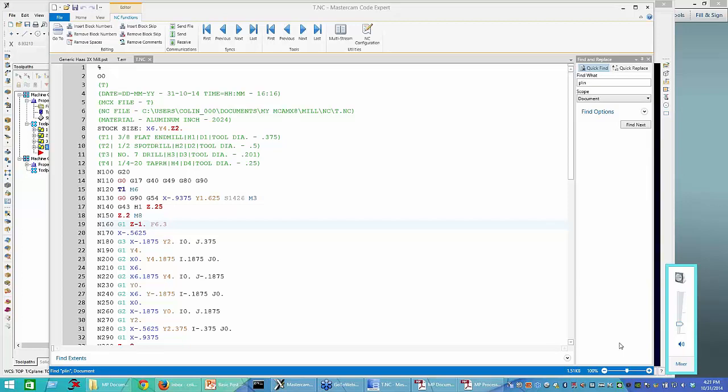One more here. For finishing toolpaths, can I output the step over or scallop height in the header of the posted file? That's coming in from Tom. Yes, you can. It depends on whether you want to do it for every operation. Right now we only output one entry per tool, so if tool 1 is used multiple times in the program, it's the first operation that uses that tool number. Of course we can have it output info for every operation.